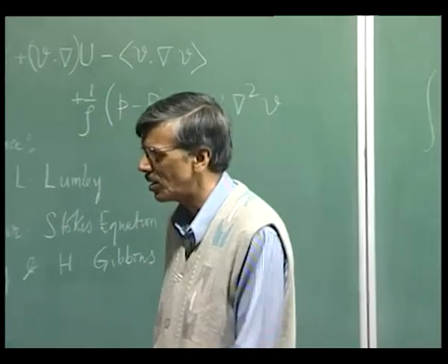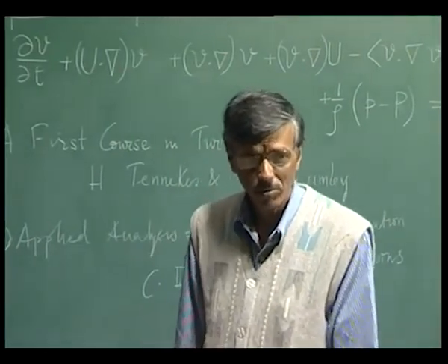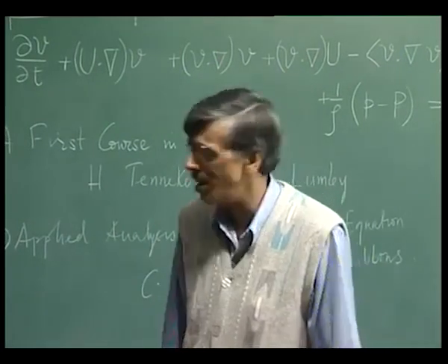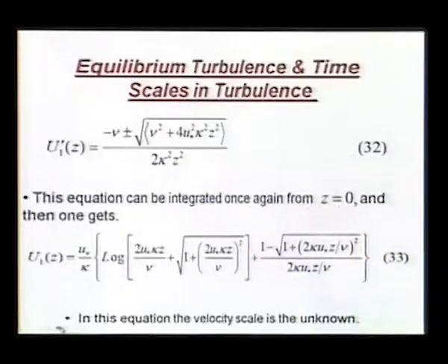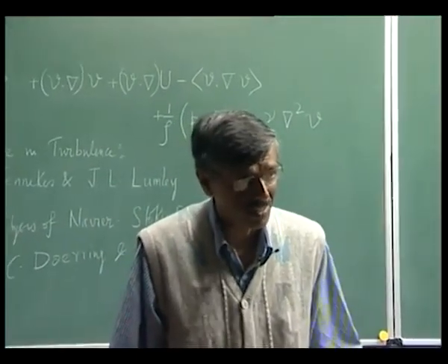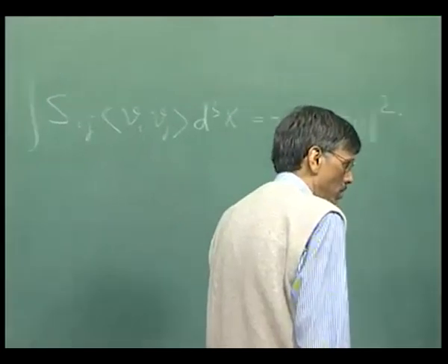Where has the thing come about? Well, it has come about because of the presence of the V1 V2, right. V1 V2, those Reynolds stress would be negligible for laminar flow. So, where does this thing come in? In this equation, that information comes in through the way we have defined the velocity scale u star, because the tau wall has a built-in effect of the turbulence in it. The wall shear itself has information of turbulence being built in there.